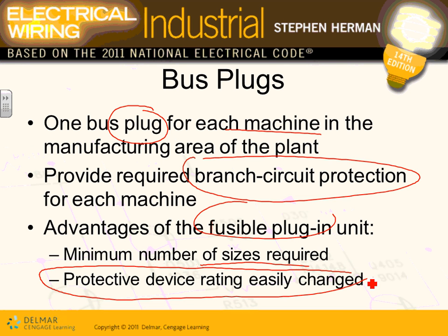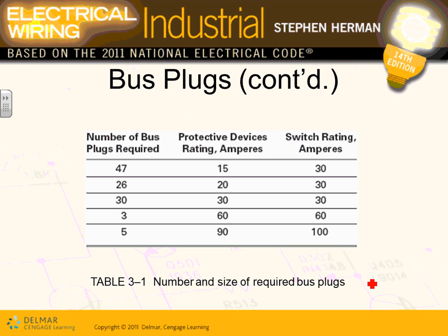You take that plug, a couple of screws, take that plug, and you have to disconnect, of course, and go plug it there. If you're to touch with the feeder, though, you have to shut the system down. This, you don't shut the system down even. The busway stays hot. All you shut down is the machine, so it's not running. So it's a great advantage. I'm so glad that we went to the field trip before we did the design.